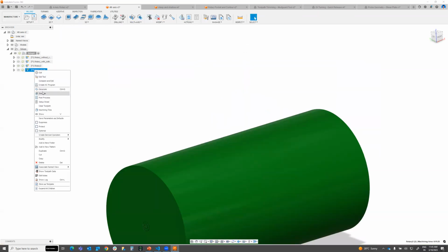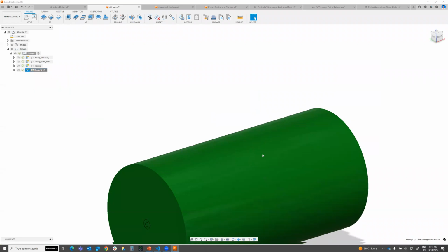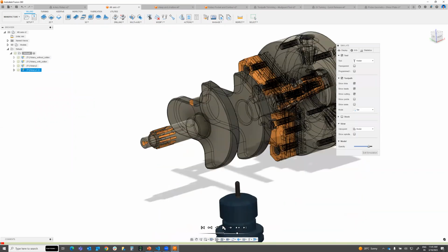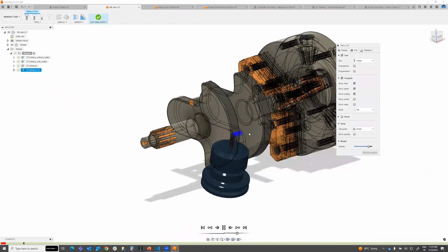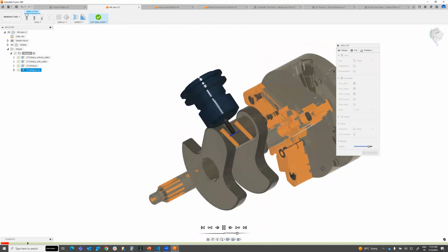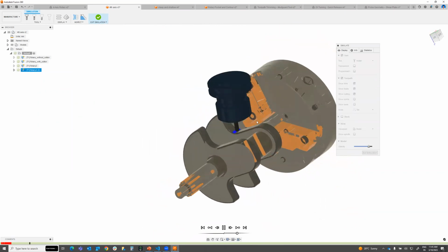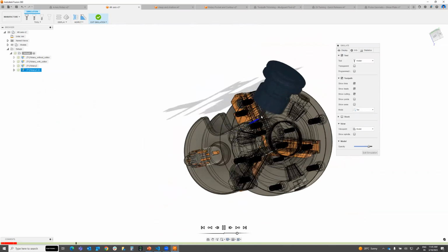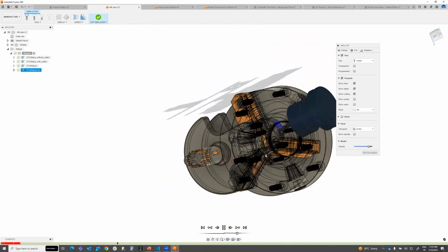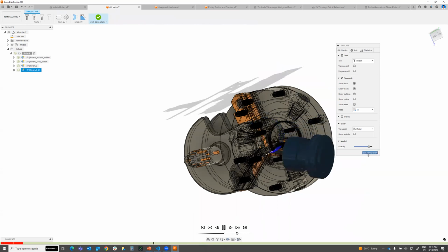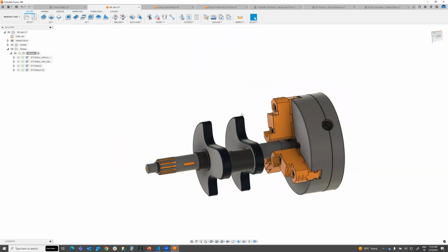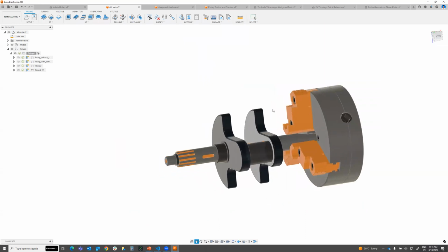Then the toolpath is tilting here. Whenever the collision is coming near to that particular area, you can see now the tool was tilted parallel to the surface. That is the difference between the collision options for the rotary as well as the 4-axis strategy.